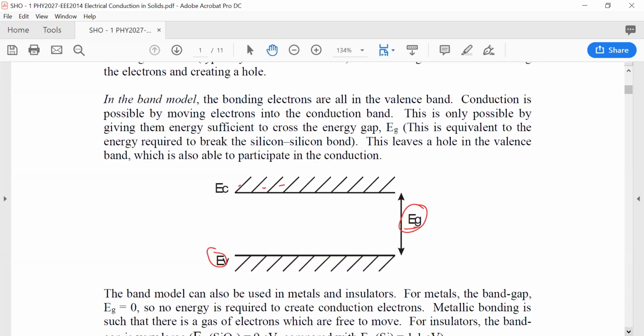Different materials are listed in different columns. You've got the different semiconductors, germanium, silicon, gallium arsenide, etc. And all of these semiconductors have each got a different band gap, as hopefully you can see and find them now. So these band gaps have an effect on how many carriers are available for conducting current. And it's why I said each semiconductor is different and generates different current and device performance, even when everything else about the device is equal.